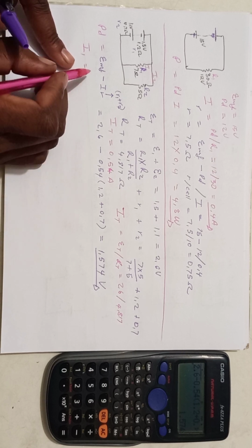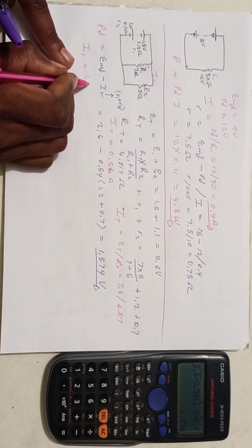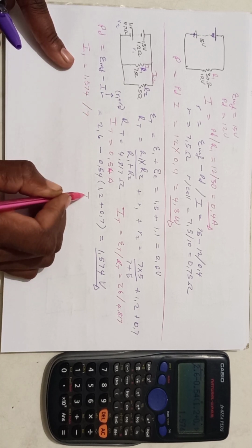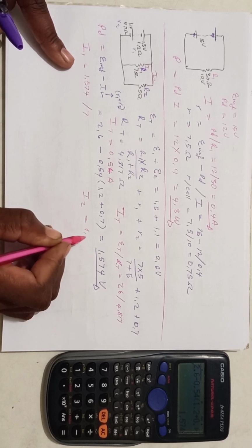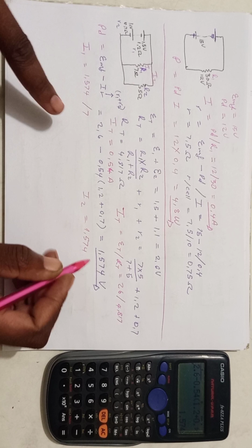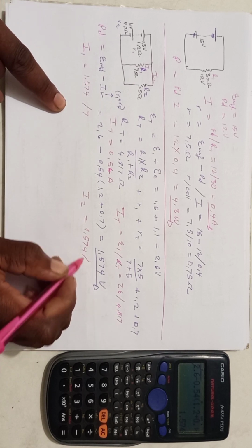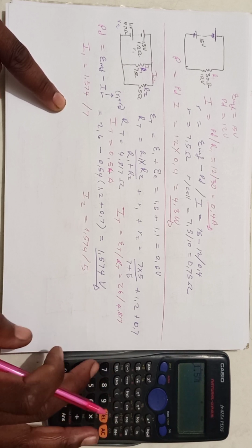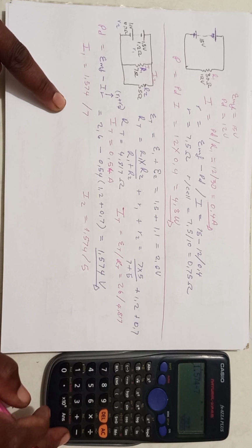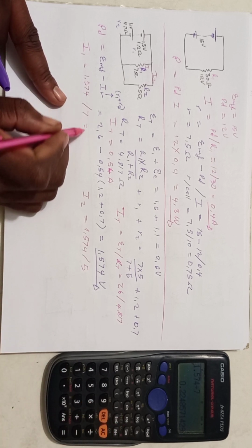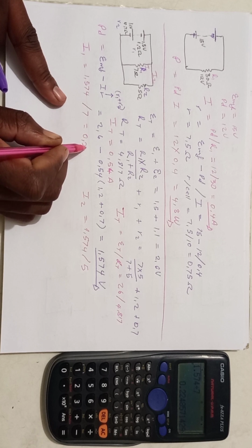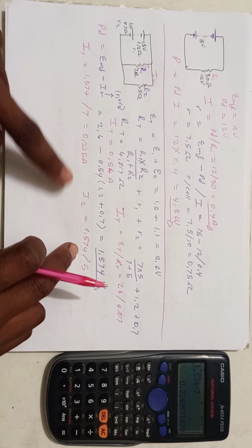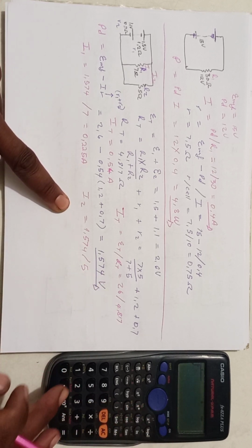We will take that voltage and divide it by 7. For I2, we would take this voltage again, because that's a parallel circuit, and divide it by 5. So let's go. 1,574 divided by 7 is equal to 0,225 amperes. A current across I2 would be